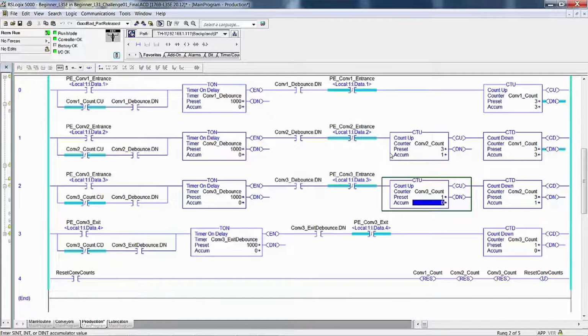Repeat the previous sequence, PE1 on, PE2 on. Look at the conveyor logic to note what is running, and then PE1 off, PE2 off. Okay, so we repeat these 2 steps. PE1 on, timed out, PE2 on, timed out, then PE1 off, PE2 off.